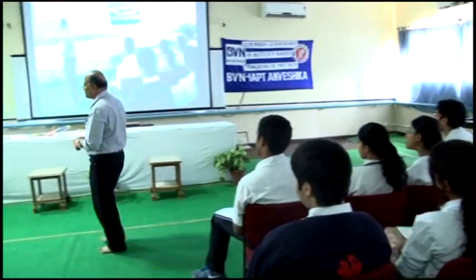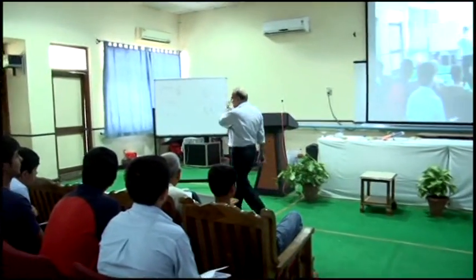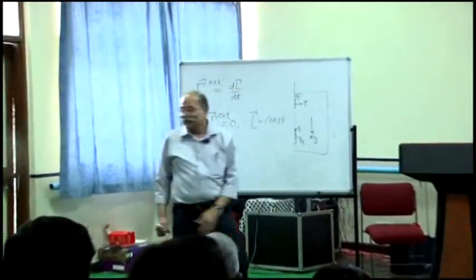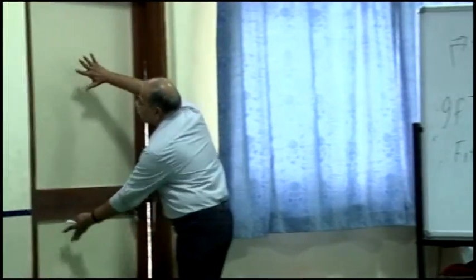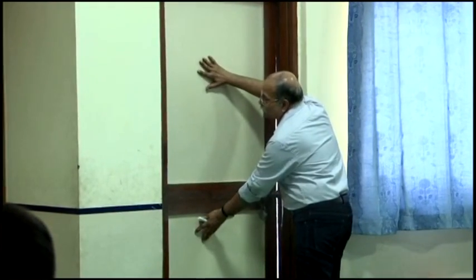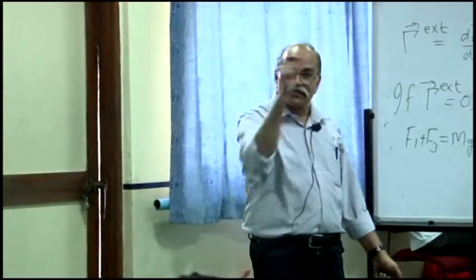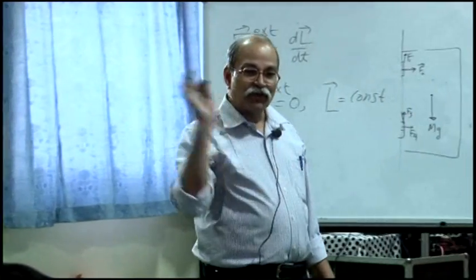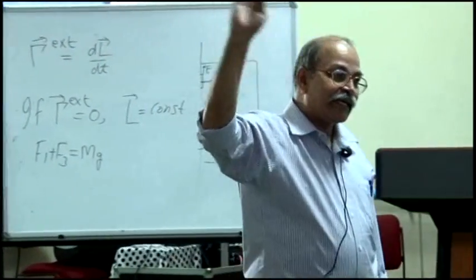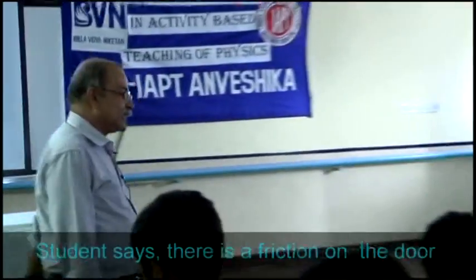So you will have forces. Now you are talking of perpendicular to this plane, right? Perpendicular to this door. From this side there is atmospheric pressure which is exerting force. On that side it is exerting force. They are equal, correct? And therefore when I am talking of total horizontal force should be 0, those two are already 0, correct? They are external forces, but then those two are adding to 0. It's uniformly distributed from the two sides, magnitude, so they are already adding to 0. Yes. Yeah.